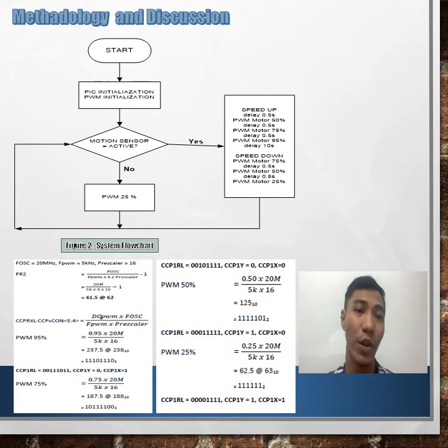The conveyor will move at only 25% of its speed when there are no bags on it. When the conveyor receives the first bag, the sensor will give input to the PWM to increase speed, moving the conveyor from, for example, 25% to 50% of its speed, then to 75% and finally 95%. The time from one stage to another is less than a few seconds.